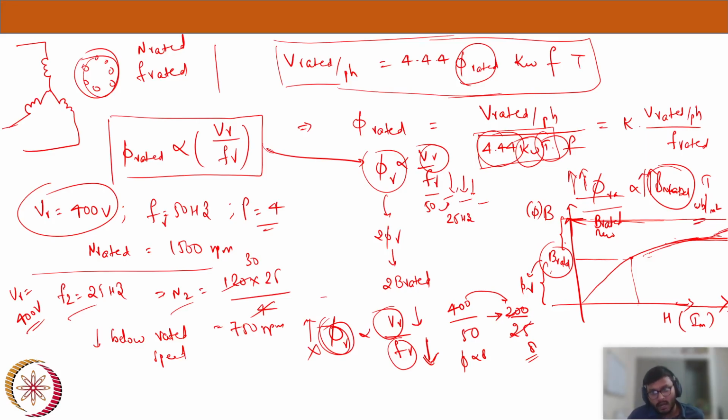That's how, because now we have a variable. How can we reduce the voltage here? That's also possible because we talked about the supply we have. It's variable voltage and variable frequency. Now we can get varied values of both voltage and frequency here. So yeah, now everything is fine. Now we will just see how my torque speed curves look in this condition, where I am able to achieve different speeds, different frequencies, and different supply voltages. How would my torque speed curve look?